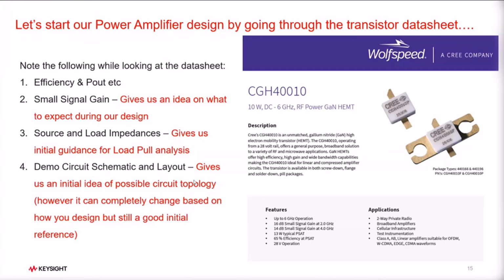If you need, then you have straight guidance, but usually you do much narrower band designs compared to how the demo board is prepared. So in a way, from a practical sense, that demo description is an overkill, but at least you get an idea about topology, how to put things in your own PCB, and so on and so forth. So it gives you some reference.